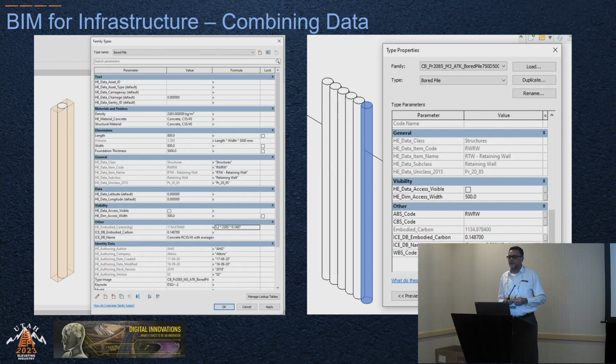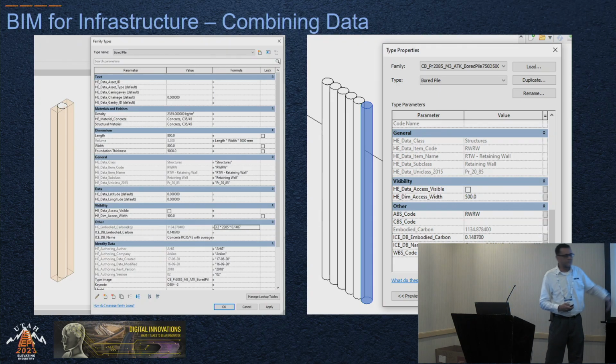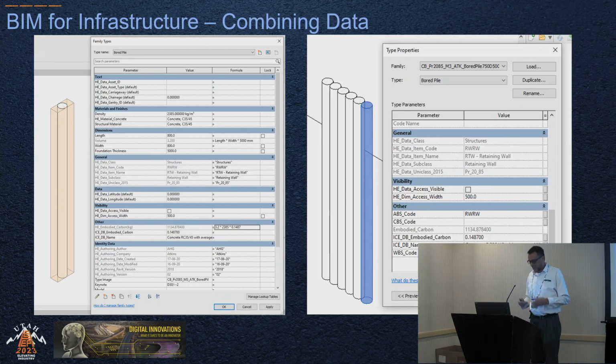We had to develop thousands of parameters and attributes on objects, okay? All of this information was translated into the IFC. So when we're talking about these drilled piers and the bored piles, there's a classification system that we used. Parent, child. Under the child, many children, okay? And that's all of this data. All this data that's associated with that object leads towards operations and maintenance and asset management.